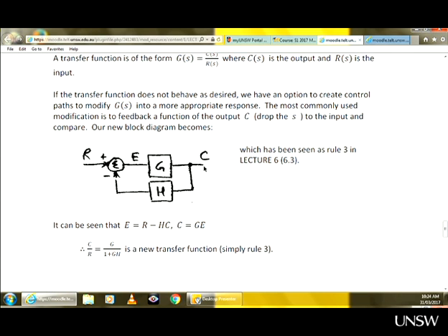If we have an overshoot, so it drops down to 19, now suddenly this error becomes a positive number. So now our system is trying to lift the temperature a little bit. So it is possible to have some oscillations, but eventually, if the system works well, we will have the output exactly what we specified by setting the input.